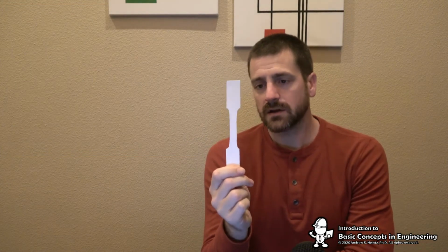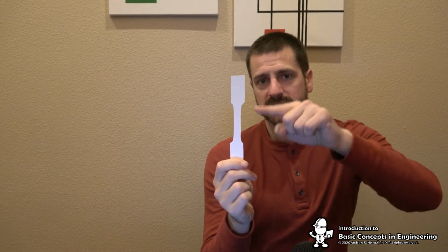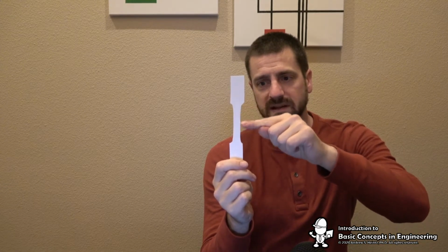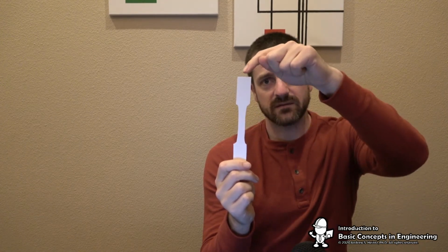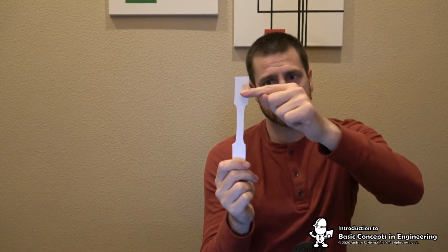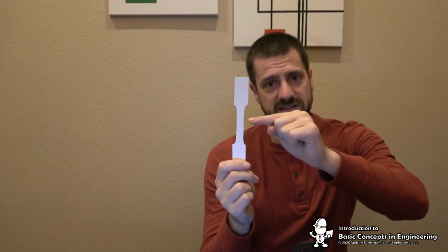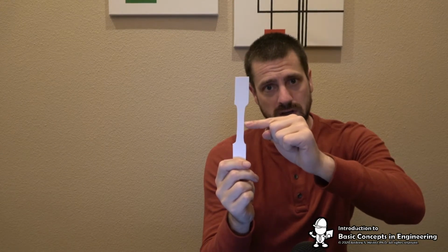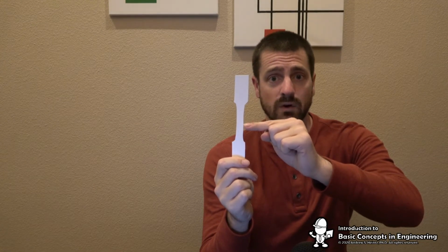So again, let's put that into context of our dog bone shape, right? If we're applying the same force to this entire material, we know that it breaks in here because there's just less material, right? And let's think about that. If we put the same force throughout this entire thing, this right here has a larger cross-sectional area than this does. Therefore, the stress that is experienced by the material here is higher because it has less cross-sectional area. Remember, in that case, you have a lower denominator. It will be a higher value.